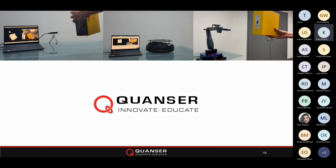Thank you, Kelly. That answers the question. Given the displacement between 2 lenses on the RealSense camera, how can you estimate the depth to an object that you detect by the RGB image? I can take this one. The advanced QUARC blocks allow you to align the depth image to any other image whose intrinsic properties are known. This way you can align the depth image from the RealSense camera to its RGB image, and then use the aligned depth image to estimate object coordinates using standard image theory.